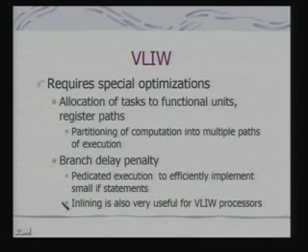In fact, in this context, inlining is also useful. What is inlining? Whenever there is a function call, there is a penalty similar to a branch delay penalty. Now, if the function is small enough, you should not call that function. You insert the code of that function at the appropriate position where it has been called. Obviously, you can realize the moment I do inlining, the memory requirement of the code increases, but the efficiency of its execution at the same time is better off.